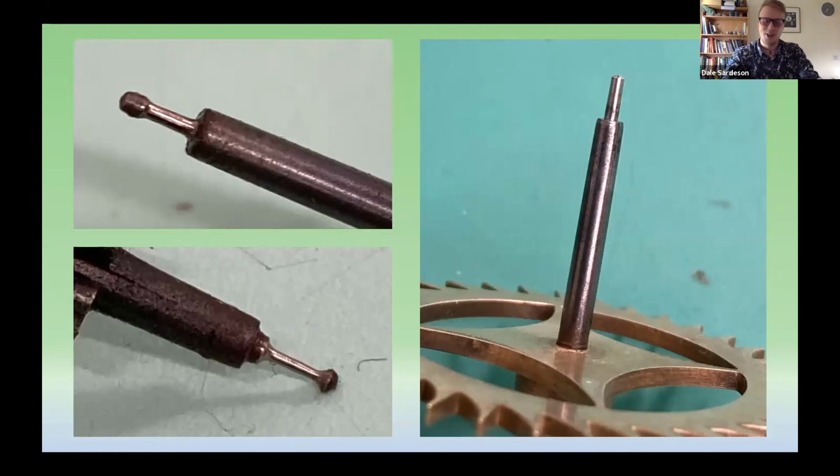Last time, Jonathan also talked about pivot polishing. As I'm sure many of you here are, I'm in total agreement with his thoughts. There's no need for a totally smooth burnished pivot. I tend to regard the light burnish to remove burrs or sharp edges to prevent further wear, but this generally means that much less bushing is required. At Allnuts, where I'm based, and a few of the other clockmakers in my local network, we refer affectionately to any scoring left in the pivots as oil retention grooves.